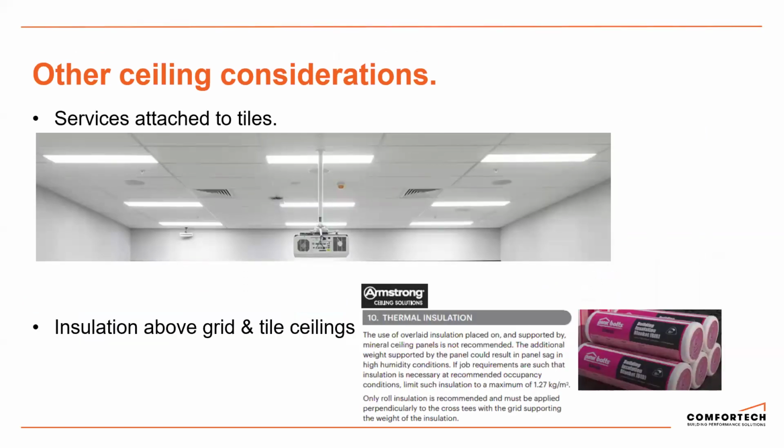So a couple of other considerations to wrap up ceilings, really. Services attached to ceiling tiles. This is really important. I can't highlight this enough. Ceiling tiles are only designed to support their own weight. For lightweight fixtures, like downlights, smoke detectors, and speakers, it's often assumed that these can be supported by the ceiling tiles. We need to refer to AS/NZS 3000, section 423 in electrical services, which refers to the fact that you cannot install these lightweight fixtures directly to ceiling tiles. What we need to do is use some supporting framing.